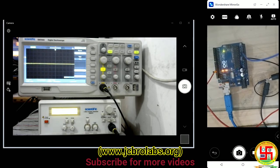So we have set up and connected our setup. The DSO is connected to pin number 13, and the function generator is connected to A0. That's why we are not getting any output on the DSO, because we are not generating anything on pin number 13. And one thing should be taken care of during this entire experiment: all the grounds should be common.